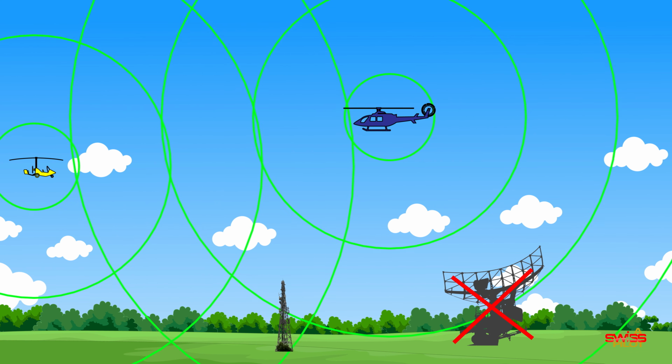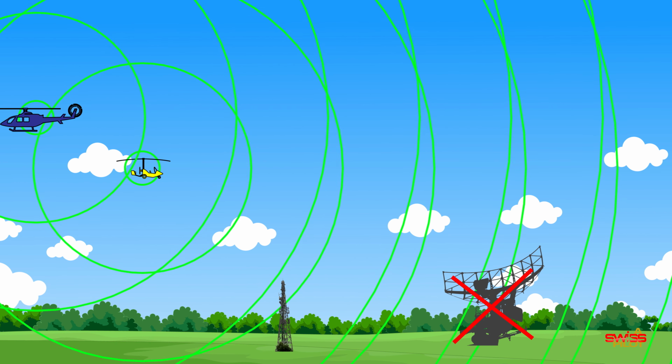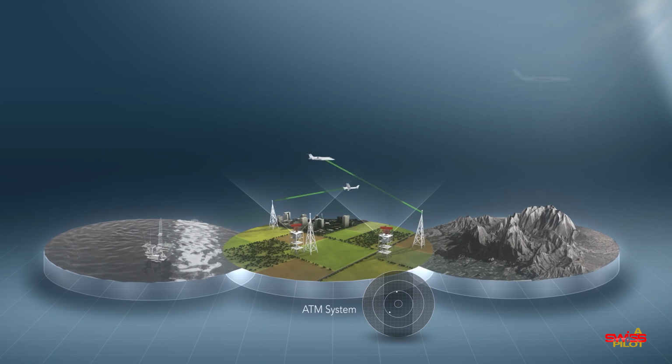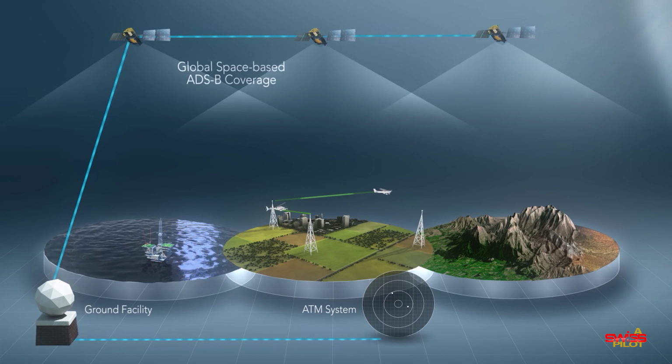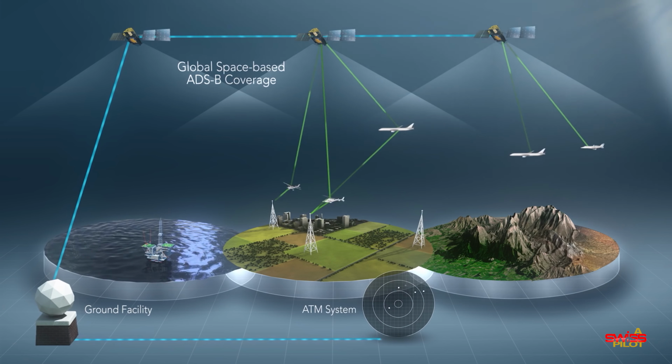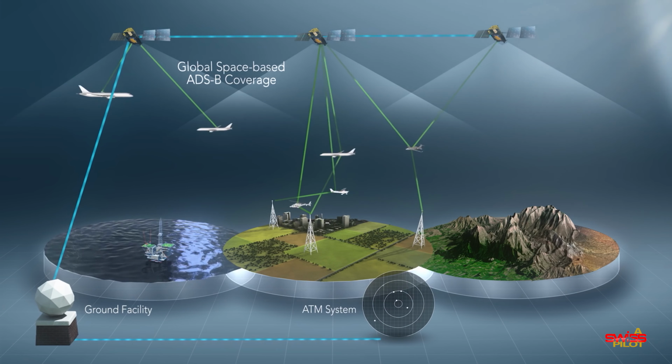Now, if you think of it, ADS-B will allow us to get rid of the classic ground station interrogates and transponder replies game that we've seen before. All that's required now is a receiver on the ground and no huge radar antenna anymore. ADS-B has a couple of huge advantages for ATC, but also for us as pilots. Radar installations are getting cheaper, controllers get an almost real-time traffic picture, also in remote areas through satellite reception. The entire traffic flow gets more efficient as the ATC's radar screens are being updated more frequently. And in the end, we as pilots are getting optimized routings and all that kind of stuff.